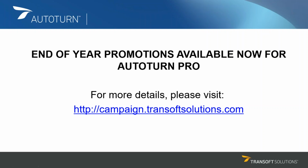You can use it. Well, IntelliPath right now doesn't work to produce reverse maneuvers, but there are workarounds, or it works together with continuous simulation in AutoTURN. So you can let the IntelliPath figure out the forward simulation and then go and click continue simulation and drive the vehicle manually to produce the reverse maneuver. So you can save some time by producing the forward simulation using IntelliPath and then switching to arc path or reverse corner path to have the vehicle at the loading dock.